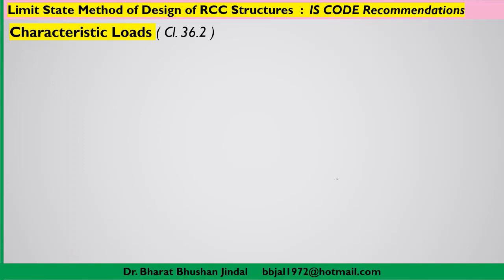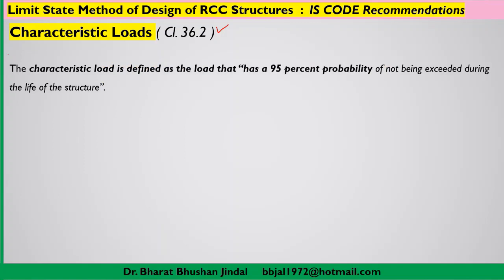In the previous slide we went through the characteristic strength. Now we are focusing on characteristic loads, for which the information is available in clause number 36.2. Let us briefly discuss this. The characteristic load is defined as the load that has a 95% probability of not being exceeded during the life of the structure.